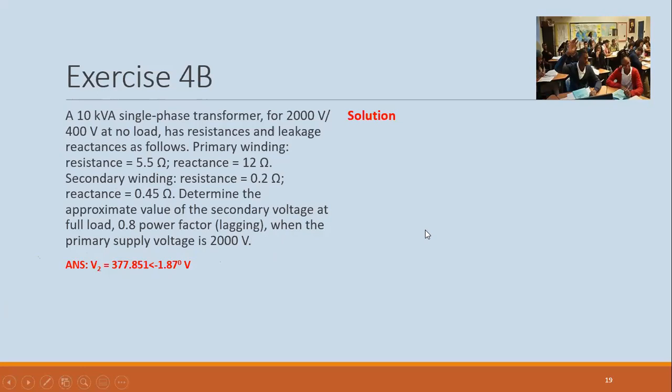So this is something that is actually going on, and it is going on continuously. As adjustments on the load need to take place within a certain band, the voltage regulator would adjust to meet the change in load to give you your rated voltage, right?